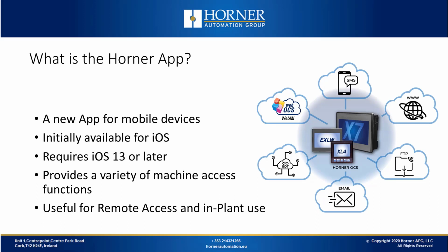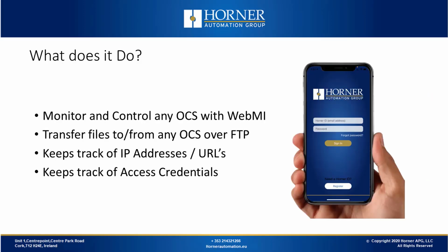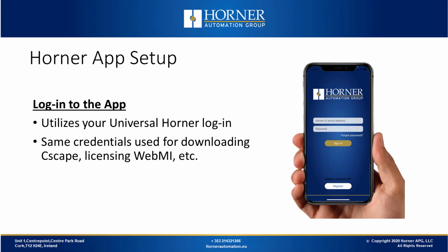Well, what is the Horner app? The app is named Fabric and is for mobile devices. It's currently available for iOS devices, with an Android version coming soon. It requires iOS 13 and above to run. The new app provides a variety of machine access functions, and it is useful for a remote access type application or for in-plant use. The app allows you to monitor and control any OCS with WebMI in an easier way than it is with a browser alone. It allows you to transfer files to and from any OCS product over FTP. It keeps track of IP addresses, URLs, and access credentials for you.